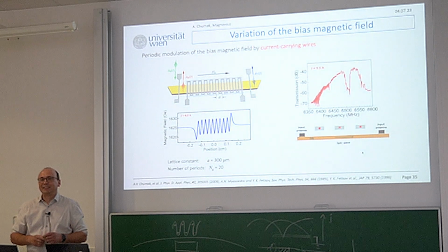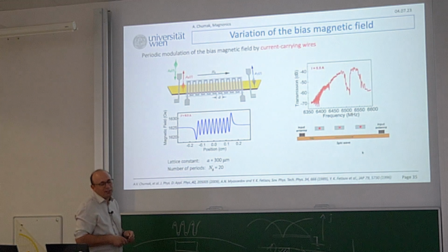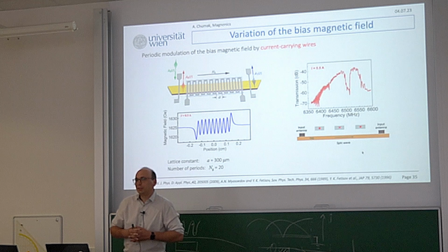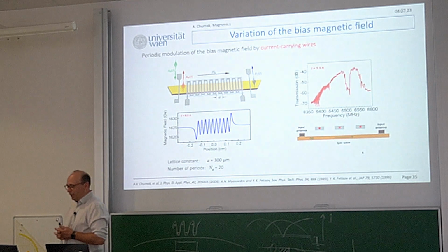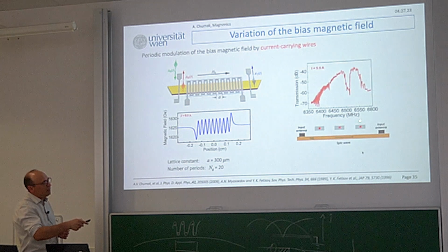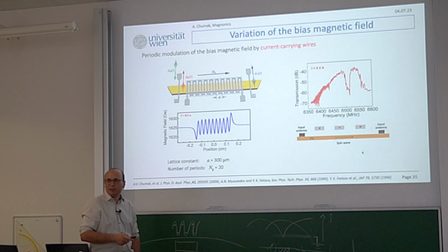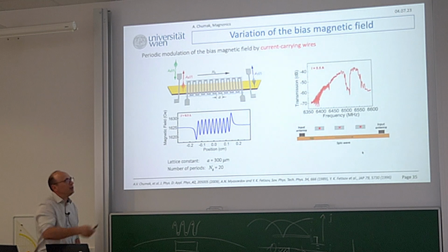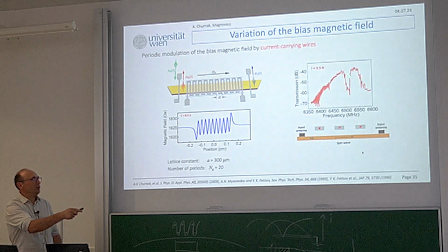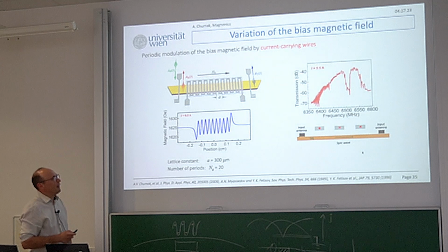Yeah, correct, you need to take a Fourier transformation, exactly like when we discussed the antenna. If you take a rectangular profile and take the Fourier transformation, you will have many delta functions. If you have one sinusoid, you take the Fourier transformation, and there will be only one delta function. That's exactly what we have seen in this experiment.